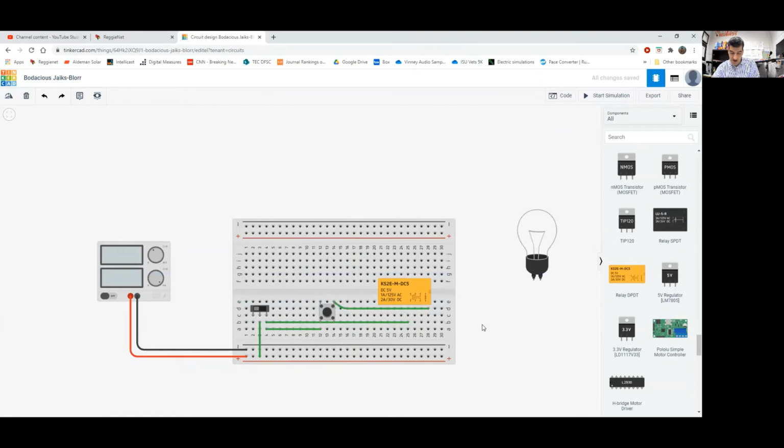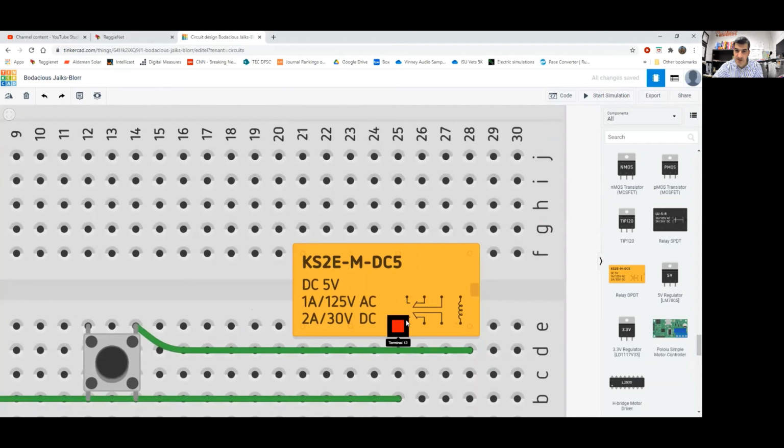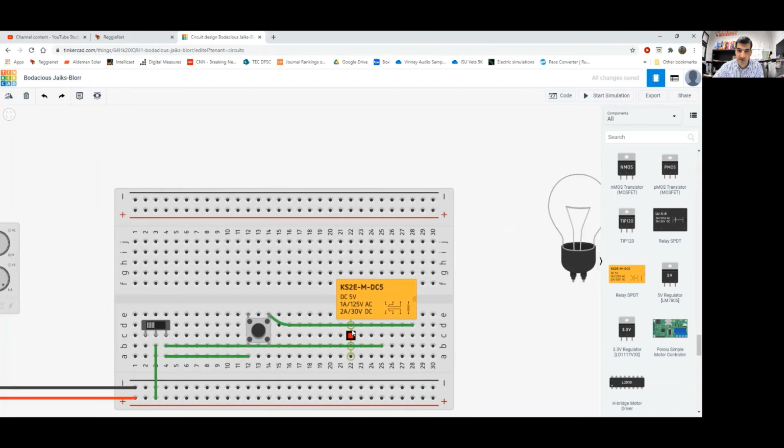And the other way that I also can energize that coil, if you look at the top rung of lab 6, I also should have a wire that goes from the normally open contact. So if you zoom in, you'll see it's the lower left contact. It's the one over here. It's the lower left one that is the normally open. You can also see that on page 41. So I need to go from one of these connections here also to the coil.